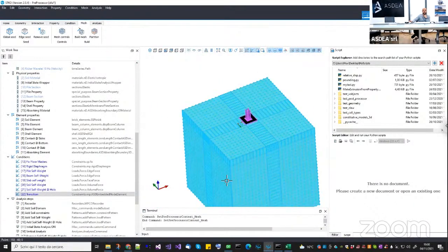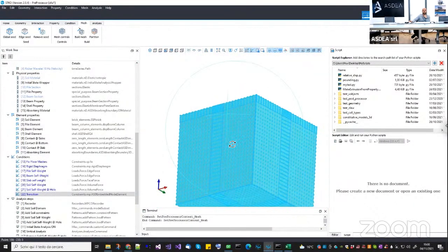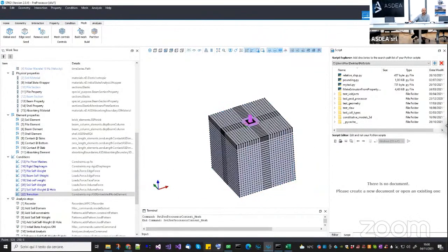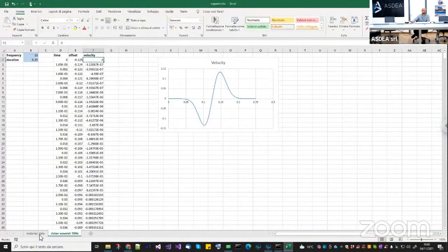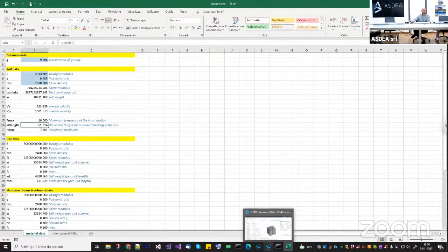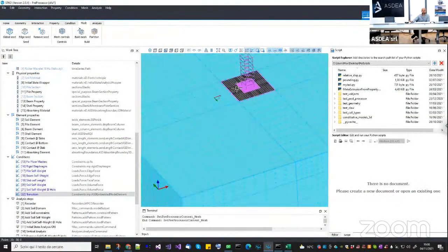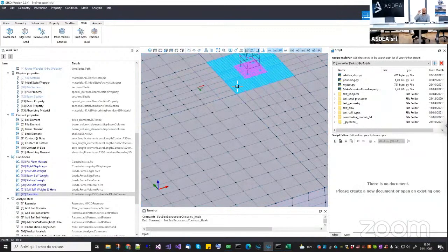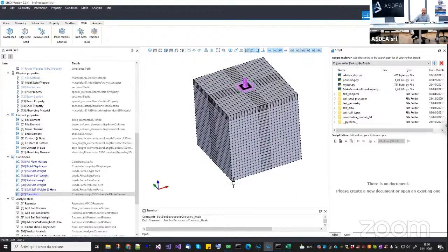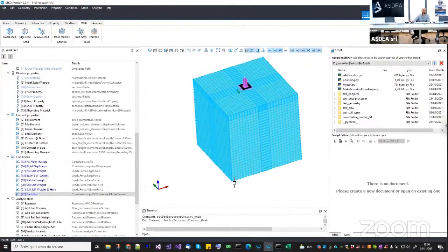And then I will apply the absorbing boundaries at the sides of this soil. Why do I need this one, which is so large? Because as I told you, the Ricker wavelet that I want to apply has a total wavelength of 61 meters, while the detailed soil here is only 15 meters. That's why I need a soil depth which is at least larger than the total wavelength, because the wave needs to completely exit the input. It should hit the free surface and go back, okay?